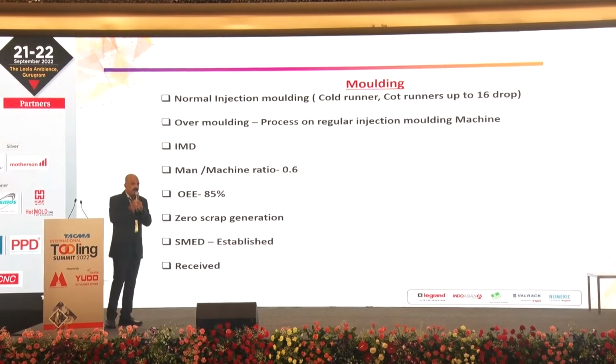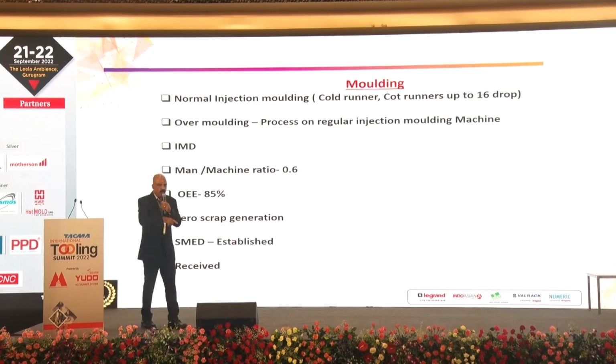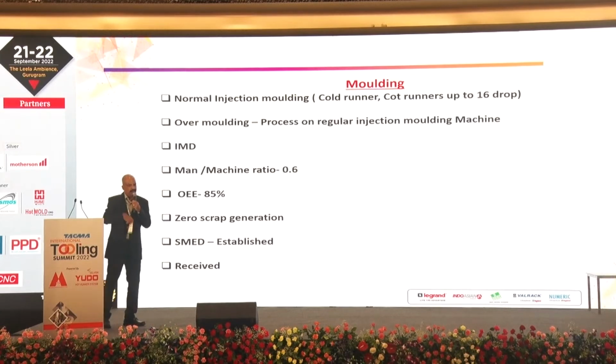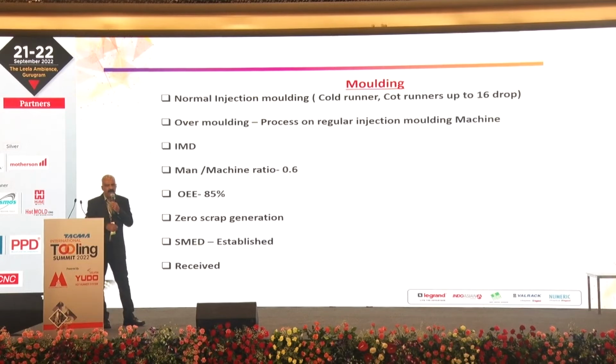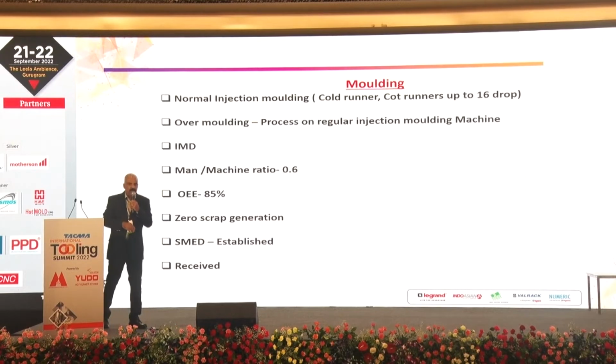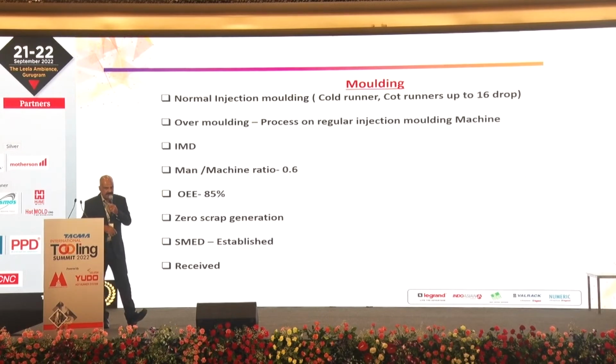We have an extra MTC near the machine in the tool room. We have an allocation on the machine. That mold will start preheating before loading. So we avoid that setting, and we have automatic setting, hydraulic clamping, everything is done. So up to 80 ton, we can change in 9 minutes, and up to 15 minutes for the machines above 80 ton, because bigger molds take a little more time for the startup. And of course, we received that award.